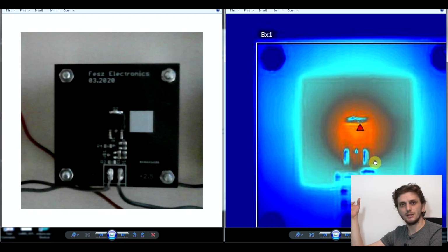What I'm trying to say by this is that depending on the color and the surface of your solder mask, so of the PCB, you can have better or worse thermal performance. Again, this will not be a highly significant value, so you will not be able to dissipate tons and tons of heat through this method, but this might help if you just need a little bit more power dissipated.